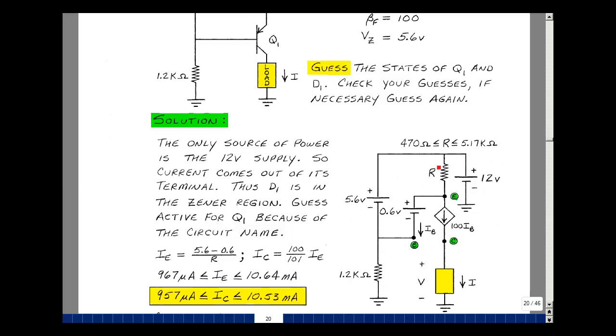I'll put a resistor here, R, that has the resistance of 470 plus the pot. But when the pot's set to 0, this becomes 470. And then when you go to the other extreme end of the pot, where you get 4.7 k, you can add that to 470 and get 5.17 k. This resistor is going to be varying between these two limits. This will allow us to adjust the current source. And then down here is my load. I'll label the voltage across it V, and then of course the current was defined as I.